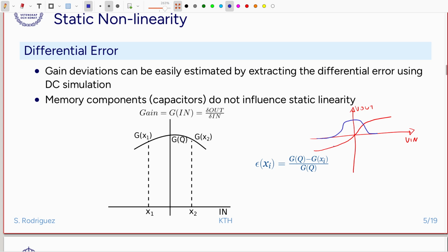So we see that very strong distortion or clipping distortion will happen at the borders, and when the system is entering weak nonlinearities, we will get the nominal amplification, the nominal voltage gain that we are designing for, and that is typically centered around the origin of our system. So we derive this signal and then we obtain the following curve, and then we can extract an error.